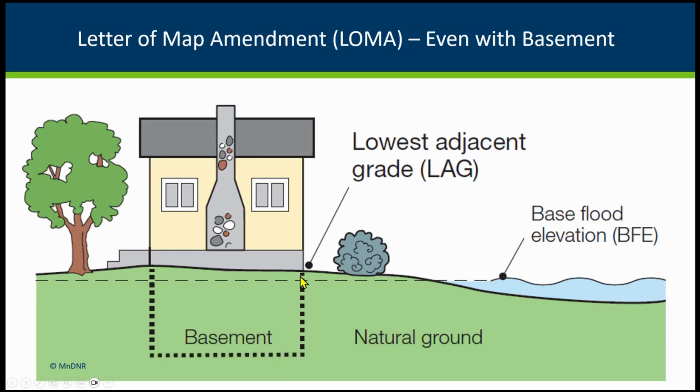In many of our older buildings, they may have had basements. That was legal back then. If they're in a shoreland or in a floodplain more recently, we should not be seeing basements below the base flood elevation. They should be meeting our regulatory flood protection elevation. But if it's a pre-FIRM building, then they can still get a LOMA, but this will be a consideration if they go to do additions or major improvements.